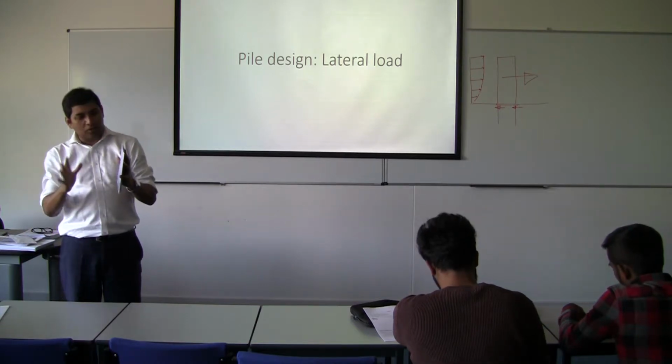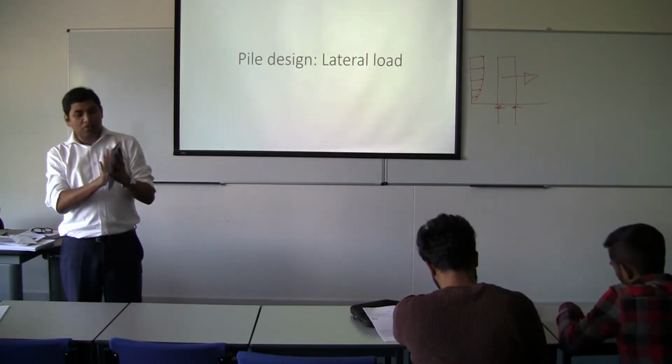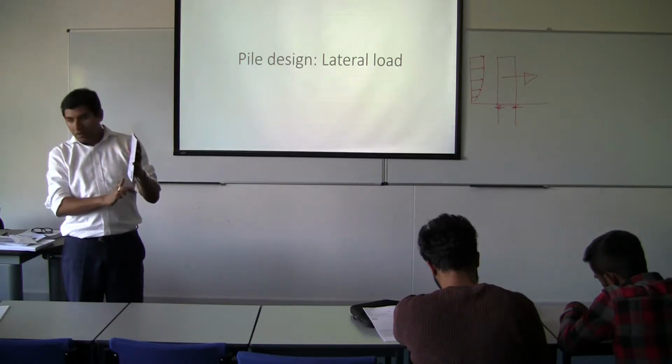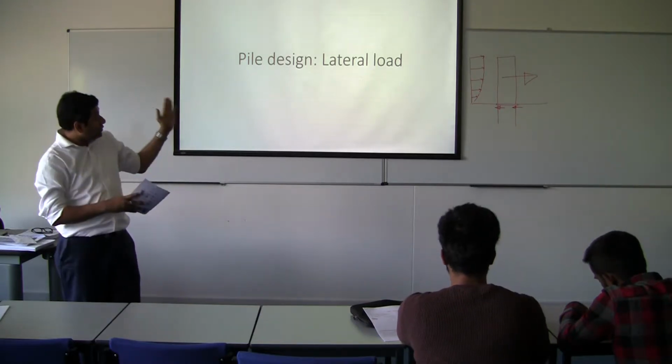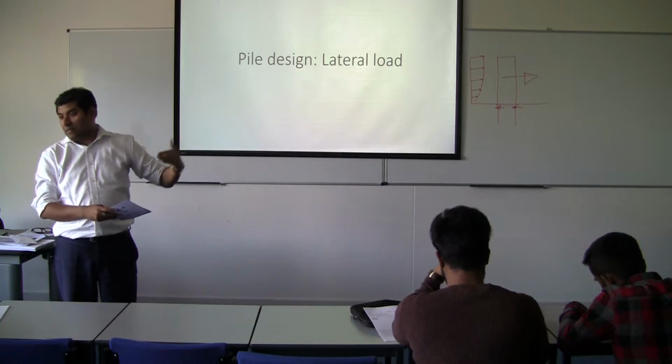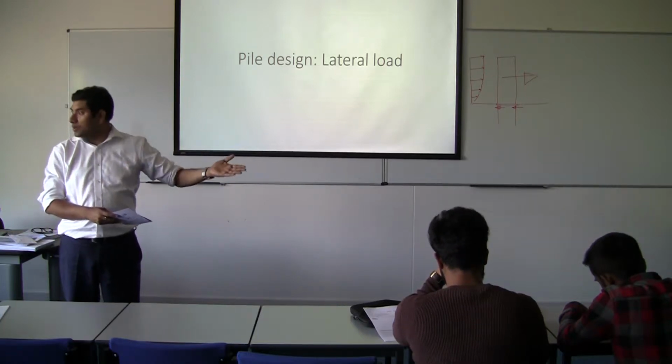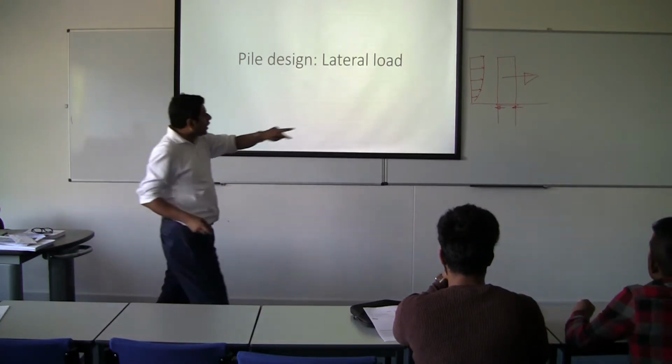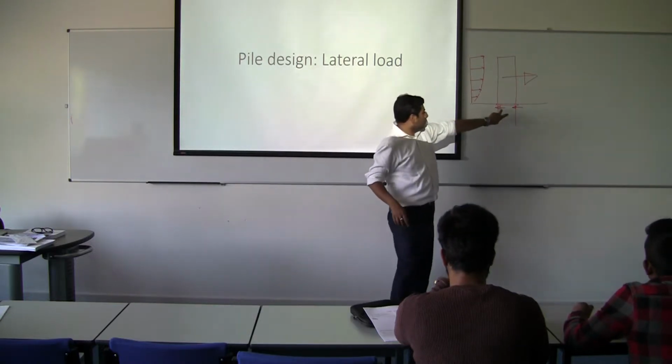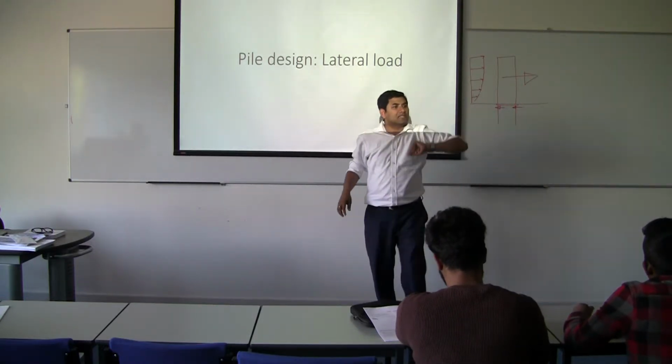Once you know the wind speed, you can work out the pressure. Once you know the pressure and the area, you get the force. Once you know the force, that force has to be resisted by the piles, and you can work out the lateral loads, right? Okay. Other examples of lateral loads.